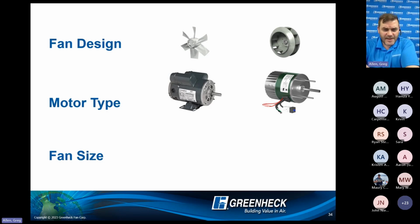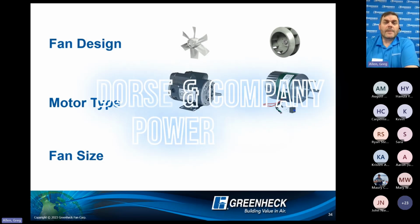When you get up into the three-phase world, three-phase AC motors are much more efficient. But there are also EC motors that are even more efficient up in that range. To give you an idea, a 2-horse AC induction motor is usually around 86.5% efficient, which is really good. An EC motor at 2-horse, you can get upwards of 91% efficient. So your gains are smaller, but they impact the wallet more as far as savings, picking up that 5 or 10% on that end.